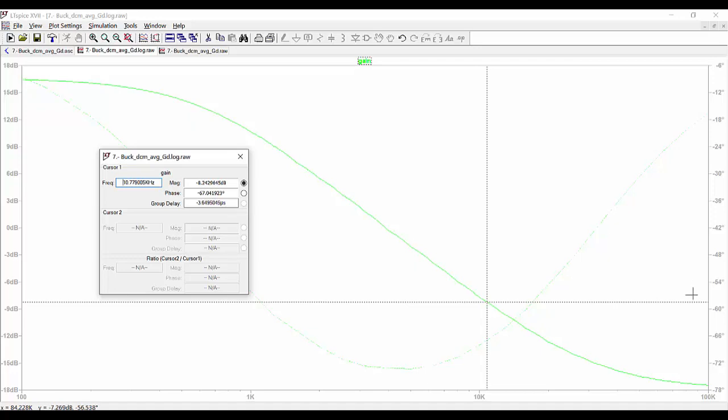And now we can see that we have no problems here of noise, obviously because we are not simulating the switching frequency, we are not simulating what is happening at each switching period. But we know that in reality these values close to the switching frequency and beyond half of the switching frequency are not real in an actual converter due to the switching behavior.